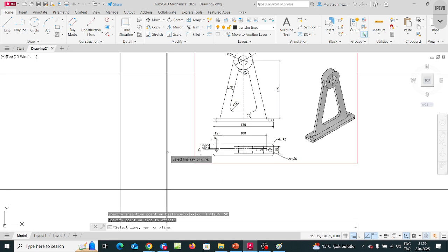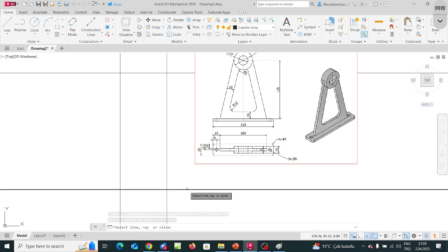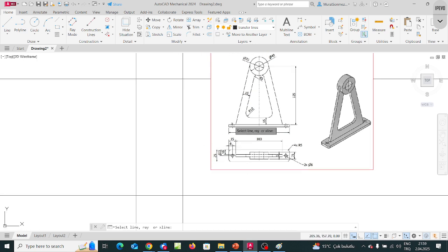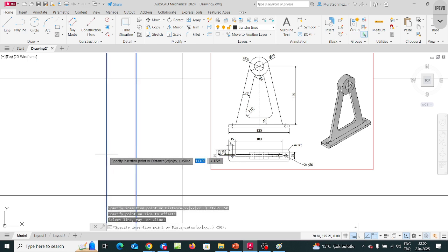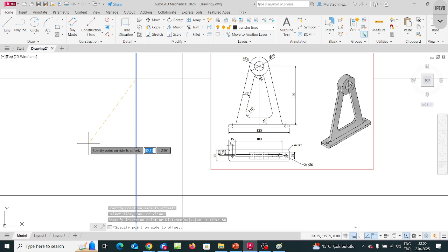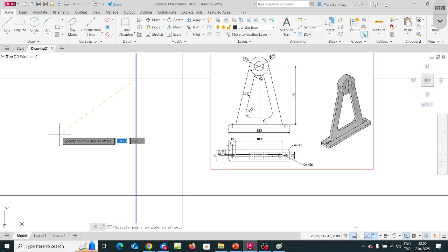This parallel transfer line and that parallel transfer line intersect each other over here. It is point B. Relatively, to be able to mark this corner point, I'm going to use this vertical transfer line as the reference. Location dimension is 50, but the point to mark is at the left hand side of the transfer line that passes through the center of the circle. So move the cursor to the left and then make a click.